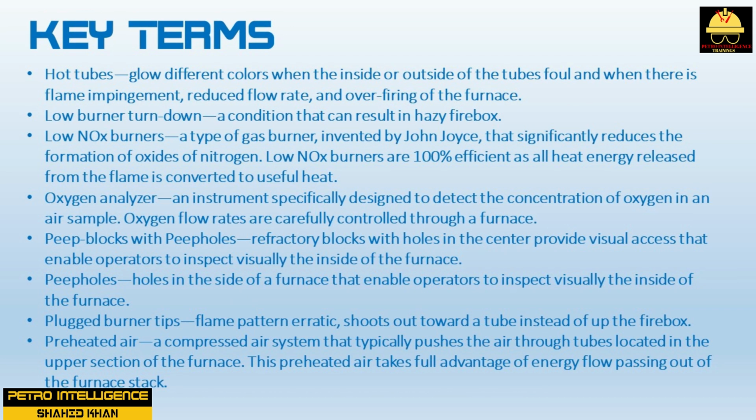Hot tubes glow different colors when the inside or outside of the tubes foul and when there is flame impingement, reduced flow rate, and overfiring of the furnace. Low burner turn down is a condition that can result in hazy firebox. Low NOx burners are a type of gas burner, invented by John Joyce, that significantly reduces the formation of oxides of nitrogen. Low NOx burners are 100% efficient as all heat energy released from the flame is converted to useful heat.